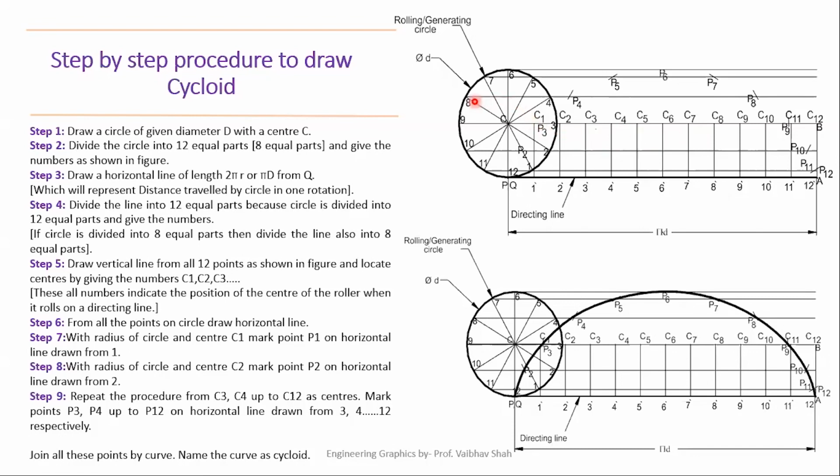Now from point number 8 and 4, you have to draw one line parallel to this center line like this. After that, you will draw one more parallel line from point number 5 and 7, like this, which will always be parallel to your center line. And once again, from your last top point 6, you have to draw one parallel line from this 6 itself. Now, this is the basic construction.